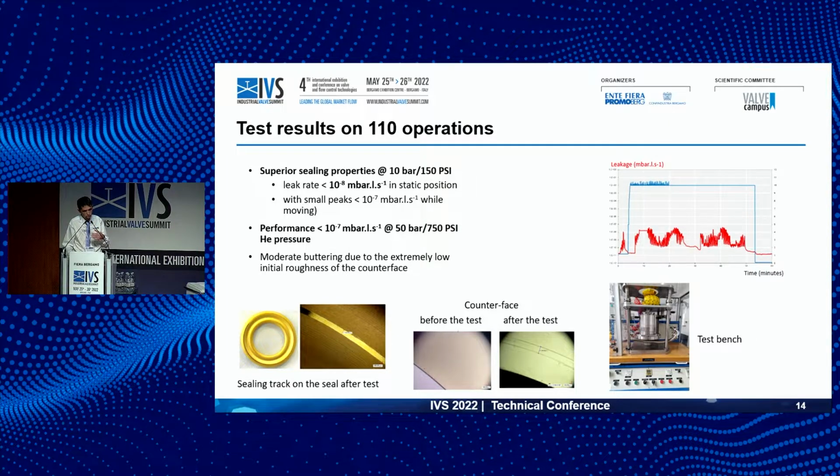That's true that the limitation of this concept is that after 200 operations, we observed that nevertheless we had some wear of the surface. As I was telling at the beginning, we are always sliding at the same place. So there was no opening and closing of the valve. We are always sliding at the same place, but with time there is some friction and we started to lose performance. But for some applications, typically with high temperature, it can be very useful.